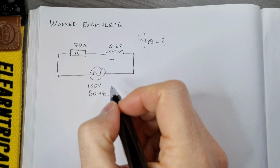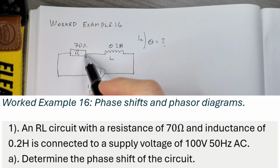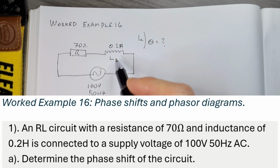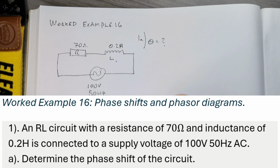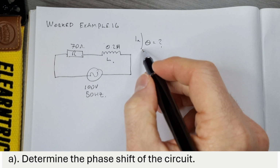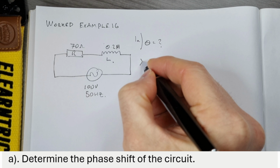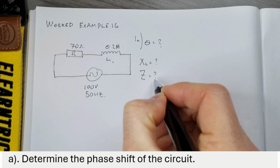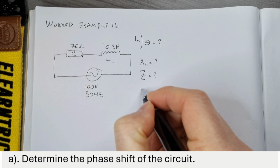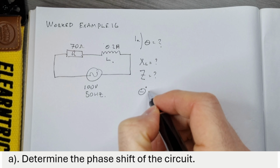Worked example 16, question 1a. An RL circuit with a resistance of 70 ohms and inductance of 0.2 henries is connected to a supply voltage of 100 volts, 50 Hz AC. Determine the phase shift of the circuit. So in order to determine the phase shift, we're going to have to work out our inductive reactance, XL. We'll then have to work out our impedance, and then from there we can work out the phase angle, the phase shift between the voltage and current in the circuit.